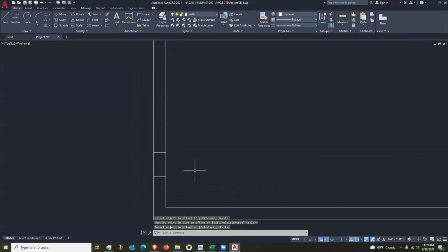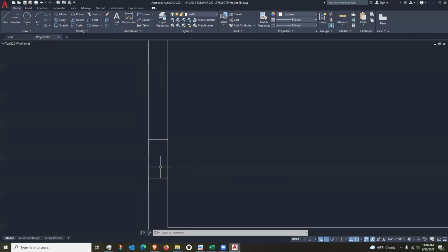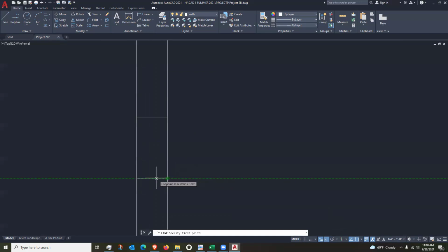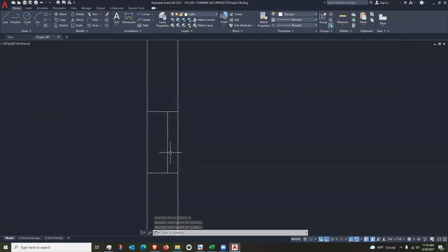Sometimes I like to put inches in because I don't feel like hitting the foot mark. And the width of the window frame itself is 6 inches. So I can offset this 6 inches, or I'll do the offset tracking right here. I'll just hover over here and then I'll move over, I'll type 6 and then go up perpendicular. So there is the depth of my window.